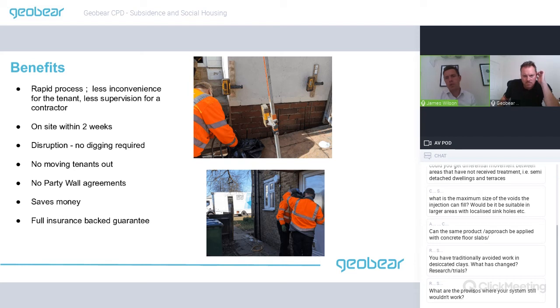We know how much the material expands because we know the exact expansion rate of it, because we developed the resin. But we also monitor very carefully, with a huge degree of accuracy, how much we lift the structure up. You can see here on this picture, these are laser monitors. Where we're injecting, you can see this technician here injecting resin, and directly above him he's got this laser monitor. We project a horizontal laser on that monitor.